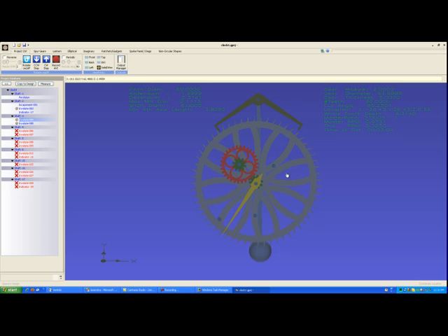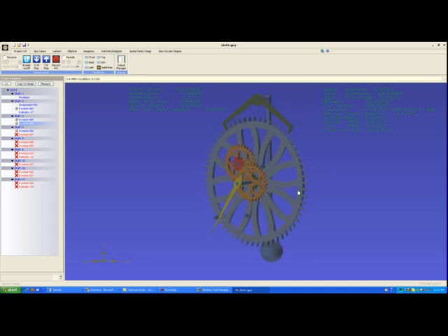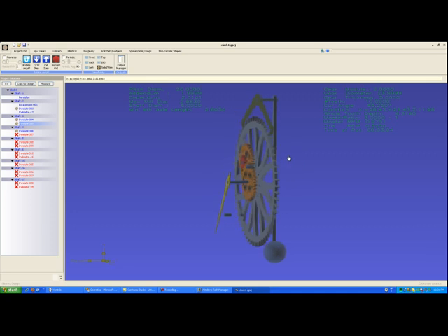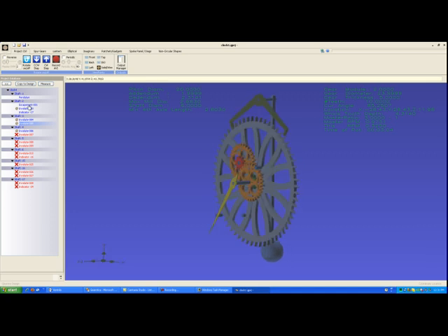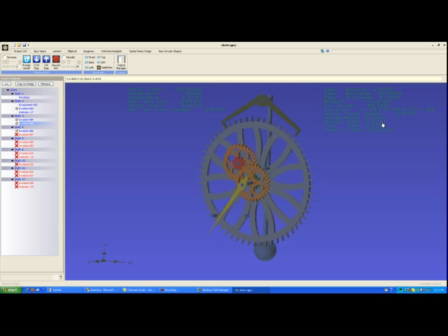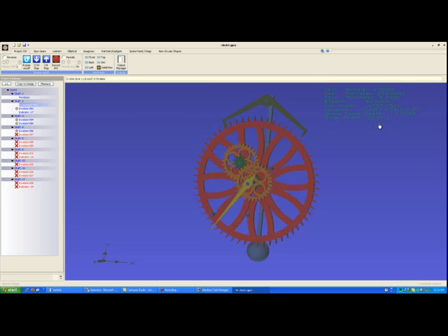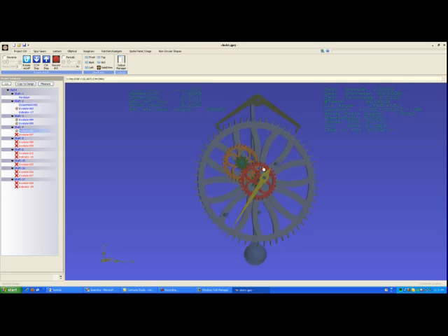Of course, this pinion that I just added also has a rotation time of 3 minutes and 4 seconds because, of course, it's bonded to the previous gear. So I'm going to swing another gear onto that, which will swing to the center shaft. Now, this gear is not bonded to the deadbeat or its pinion. It's simply running loose on the shaft. And that gear, when we select it, we can see has a rotation time of 9 minutes. We've gone up by a ratio of 3 again. So again, we're on our way towards our 1 hour, but we're not there yet.